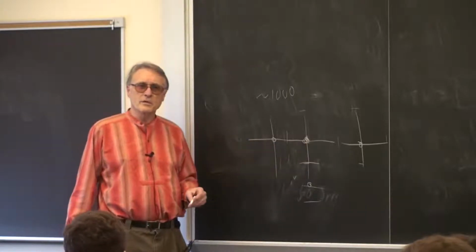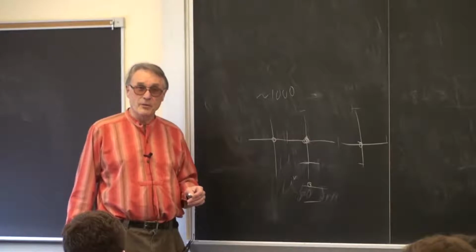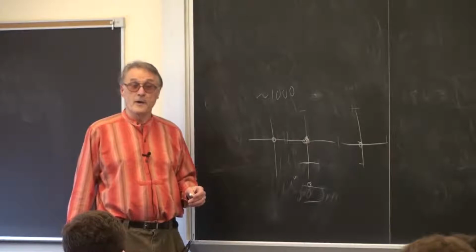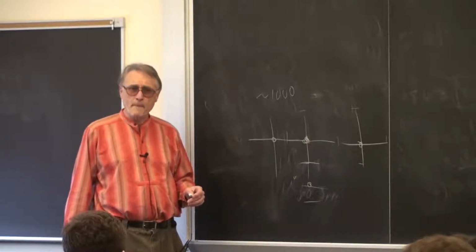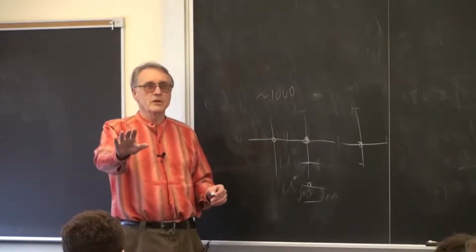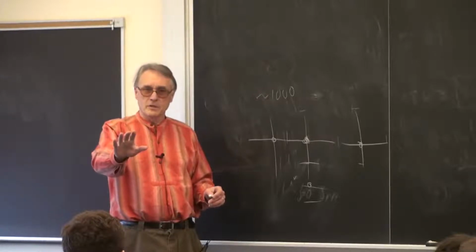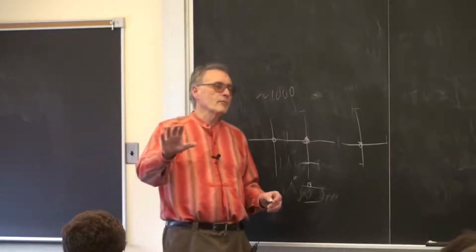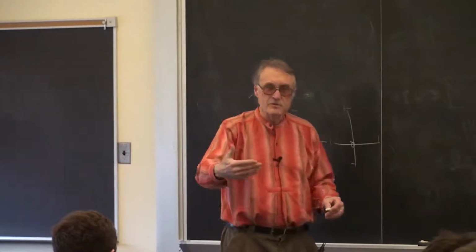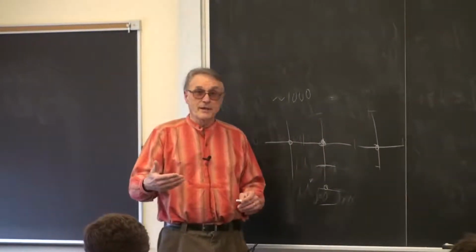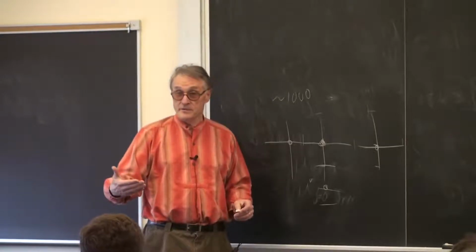Oh, that brings up an interesting question. How do you detect that a new audio sample is necessary and therefore start a new calculation? Again, there's at least 2 ways. One is, 2 weeks ago, we talked about the audio FIFOs, that the audio interface as abstracted by Qsys looks like a FIFO. If the FIFO is empty, you need a new sample. So calculate a new sample.